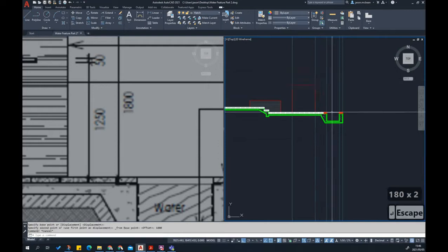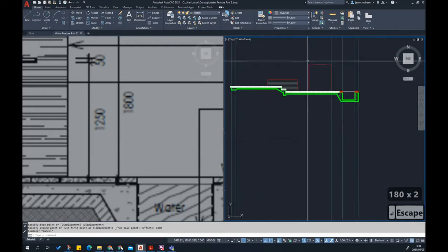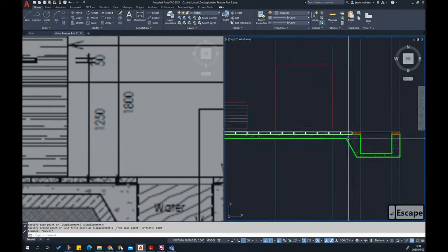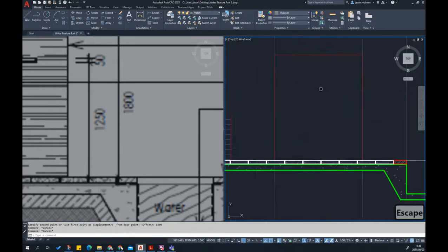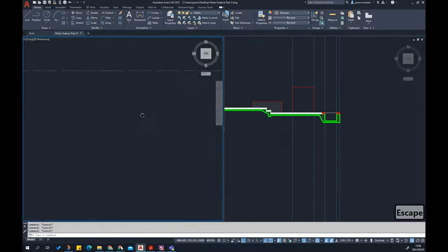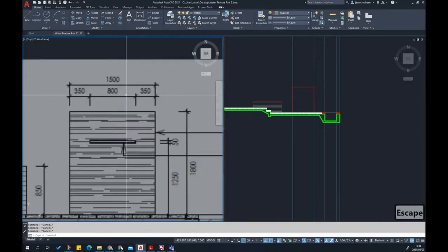Okay, generally we try and dimension off a structural object, not a finishing object. But in this case, your finish, that's fine because they'll stone it. It's a stone cladded wall. So that's just what's going on there. Okay, so here we can see, it's 800 by 50.